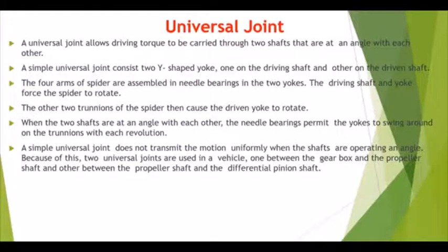Later, after your gearbox you have one shaft which is positioned to transfer your power from your front to your rear wheels. In the case of front engine drive, where your engine is positioned at the front, the power produced is transferred with the help of the propeller shaft. The propeller shaft is laid at a certain angle and is usually coupled with the help of universal joints. From this the power is transferred into the differential, which equally distributes your power to your rear wheels, and then your rear wheels move while your front wheels follow the rear.